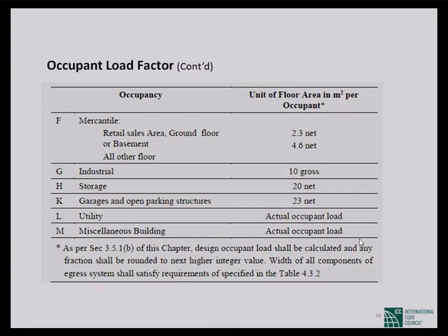There is a book written for garments factories as an NTC guideline book. In that book, a concession is given for garments factories. Actually, this data for NFPA, this data from BNBC, is not suitable particularly for the sewing floor of the garments factory. It is good for NFPA as far as the factory is a general type of factory, not a high-density factory. That's why garments factories need special documents, special recommendations for this density.